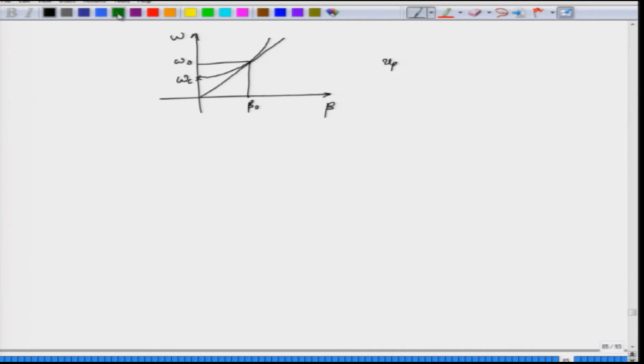However, to obtain ug, that is the group velocity, you have to actually draw a tangent here and then measure the slope of this tangent, which will give you ug. In fact, take it from me that the product ug times up will be up0 squared, okay. So, that is another way in which you can obtain the value of ug, given that you know up0 as well as the phase velocity up at any given frequency, okay.